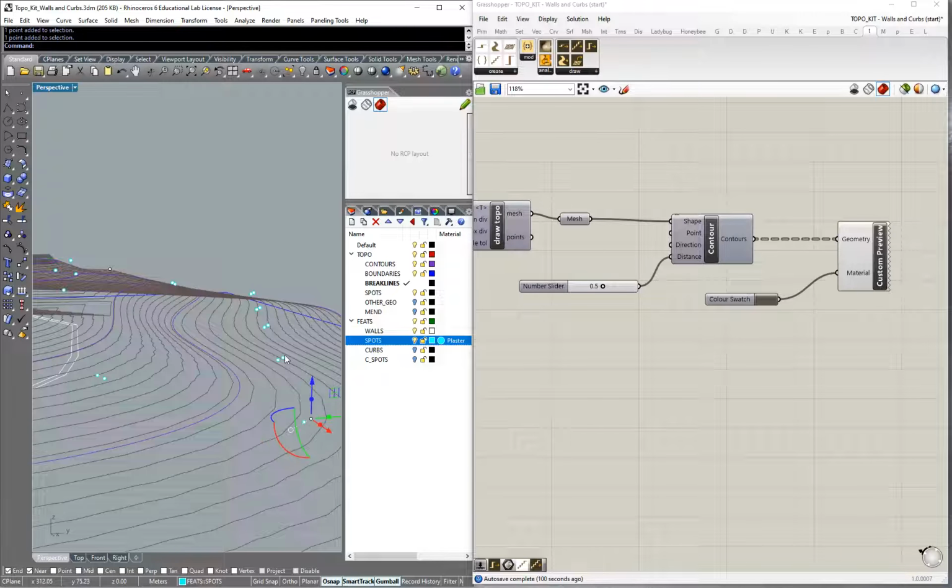The same with the curves. I created just two lines. If you go to top, you will see that they are properly aligned. Now you can use the OSNAP to just stick it to the wall exactly where you want, or you want to put them close to each other, and then we can use some tolerance to define which point and which line will be considered as a wall.